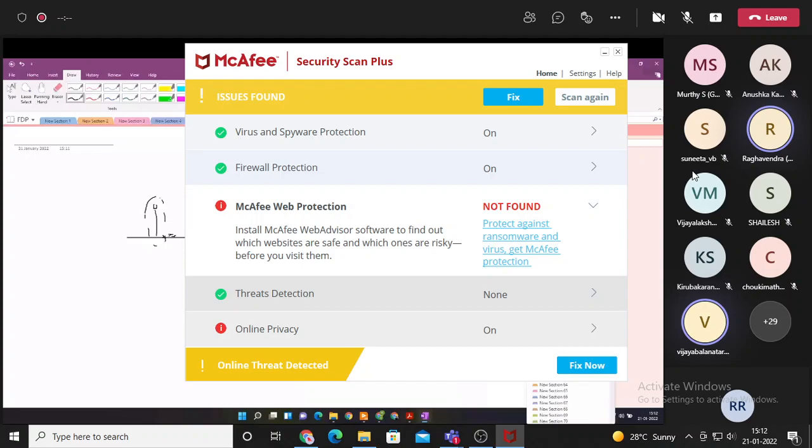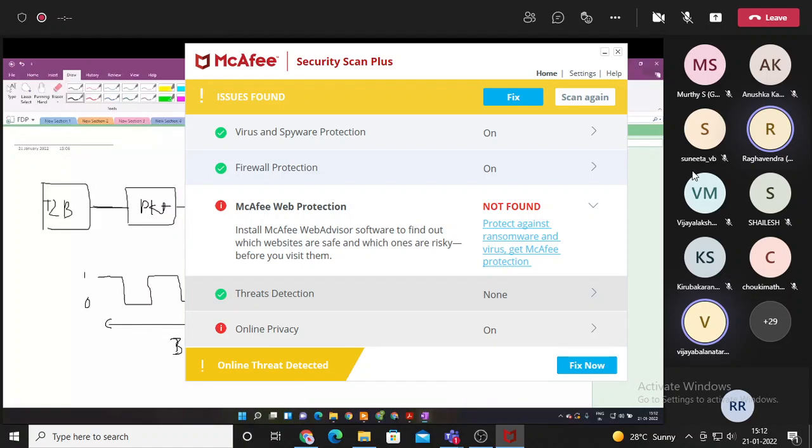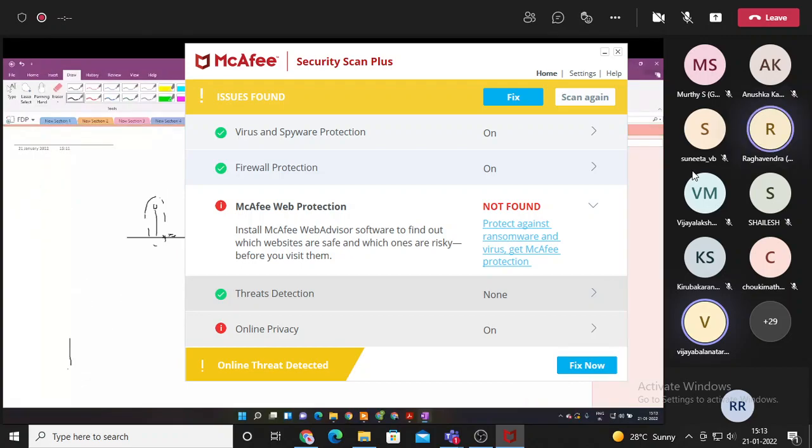So what I do at this point is I don't directly go and transmit. Technically speaking, my wave is ready because it doesn't require any further modulation. This is how the signal is supposed to look, maybe like this. But before I transmit, if I look at the signal that I'm sending out to my ADC, to my USRP, it will be either ones or zeros, right? That is what I'll be sending. So 1 0 0 0. Now I want it to look like this, right? Instead, it will look like this.